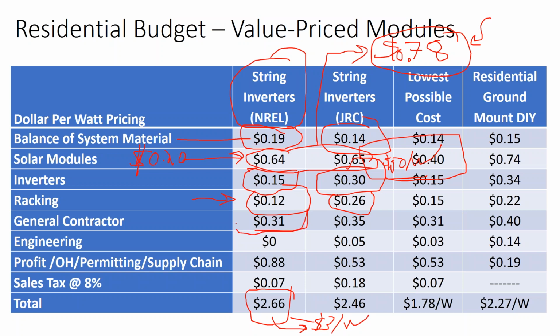Labor budget from NREL, I don't really have any qualms or issues with. When I subcontract out the install to an electrical contractor, which the only way you can sub it out is having clear construction documents, and also having one person on the project who already has some solar experience, maybe not the whole company, I'll find that subcontract price for a licensed certified contractor to be in the 35 to 50 cents a watt.